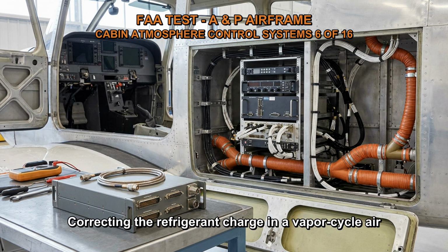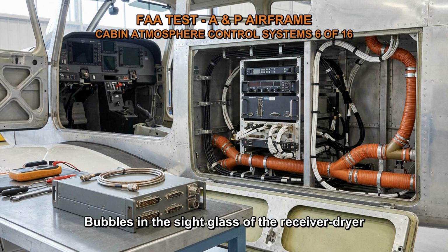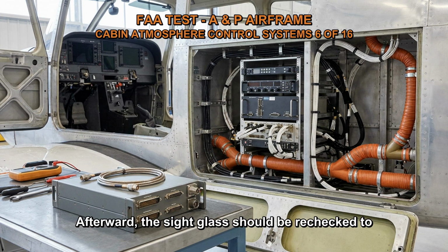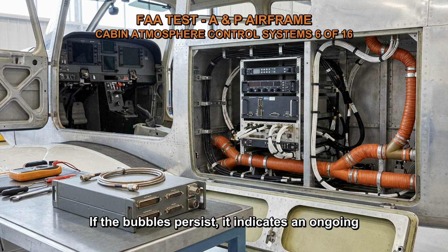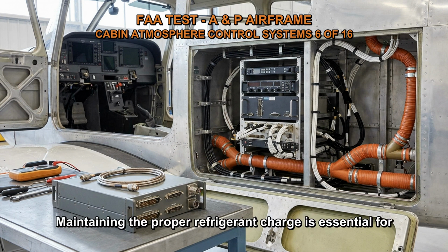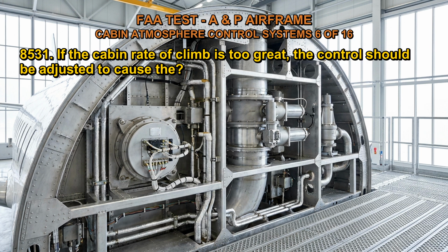Correcting the refrigerant charge in a vapor cycle air cooling system is important for its proper operation. Bubbles in the sight glass of the receiver dryer indicate a low refrigerant charge. To address this issue, the system should be operated for a period of time to allow it to stabilize. Afterward, the sight glass should be rechecked to see if it still shows a low refrigerant charge. If the bubbles persist, it indicates an ongoing issue with the refrigerant charge that needs to be addressed by a qualified technician. Maintaining the proper refrigerant charge is essential for the system's efficiency and performance.